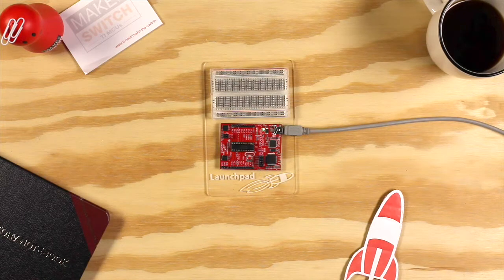Hello! In this tutorial, we're going to show you how to use analog output using the technique of pulse width modulation to fade an LED using the MSP430 G2 launchpad with Energia. PWM is a technique for getting an analog-like behavior from a digital output by switching it off and on very fast. For this example, you can either use an external LED or one of the onboard LEDs of the launchpad.